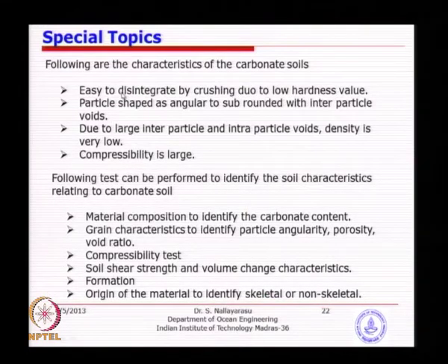It is easy to disintegrate, that means if you pick up the soil and try to squeeze it between your fingers, you will see that it does not have much strength. Particle shapes are quite angular, not much sub-rounded, and because of larger particle sizes and a lot of void space, the density will be very low. Compressibility when you apply loading will be large.